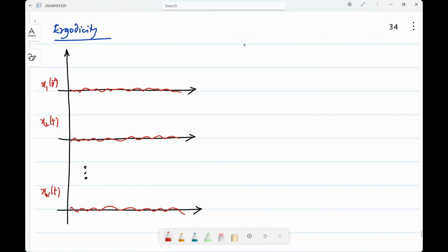Okay. Now, if I know the waveform x1, I can treat it as a known time domain signal and calculate whatever I used to calculate for time domain signals, right? Fourier transform, power spectral density, all that stuff. Okay. So let's say I do that. I calculate the power autocorrelation of x1. This is not periodic, so I have to take that limit t going to infinity.